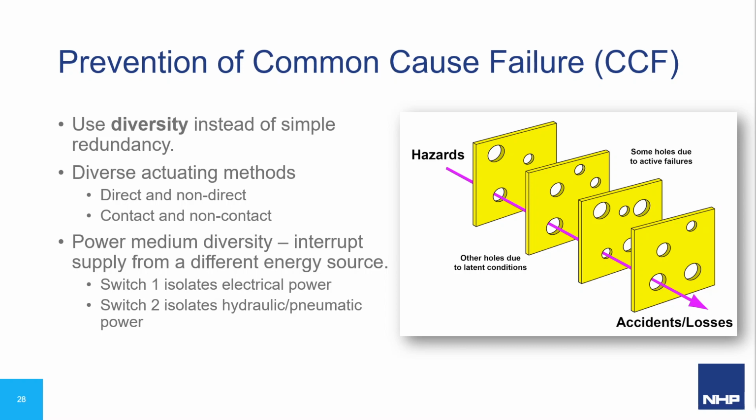The likelihood of the same type of mechanical fault, which pushes down on one actuator and releases the other whilst the guard is closed, is near impossible. But other types of diversity are available depending on the design. For hydraulic or pneumatic-based machines, multiple interlocking devices can be used to isolate electrical power, but also to close a valve to isolate any hydraulic or pneumatic power.